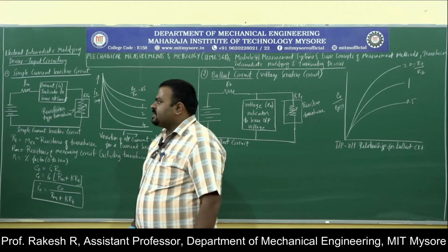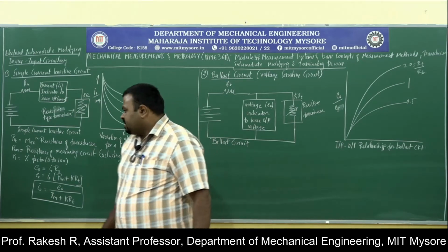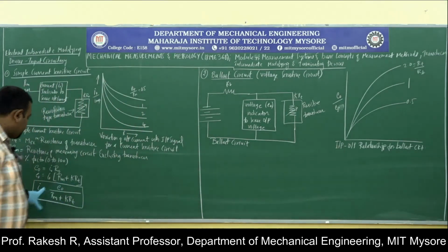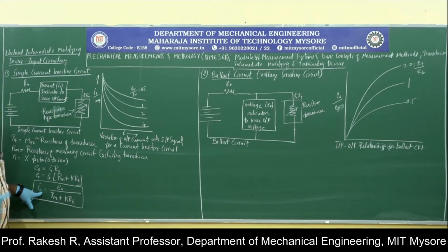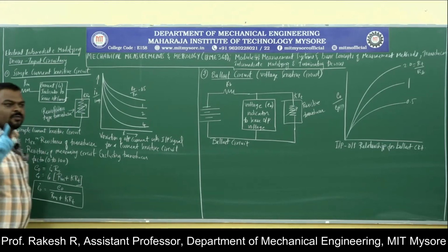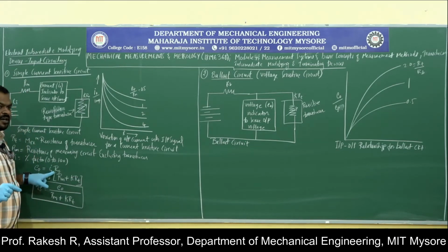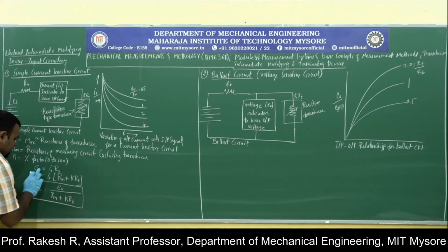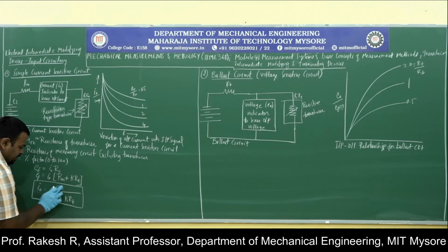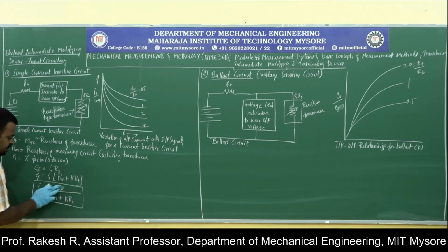In many of the cases, this output current that we have measured corresponds to this voltage, which is called EI. EI is nothing but the input voltage. Most of you make this mistake: since it is output current, you take the output voltage into consideration. No, it is the input voltage. Very important thing. Don't commit this mistake in the examination. This is the input voltage, EI.